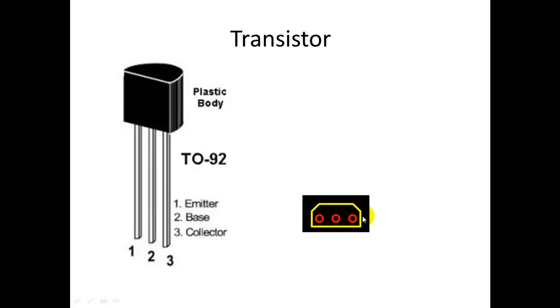It's on the top side of the circuit board, which will assist us in figuring out the correct orientation of the transistor. So here it is important to have the flat side facing down, facing this direction, and not place the transistor the other way. It could fit the other way if you place it, but it will not function because the emitter and the collector, pins 1 and 3, will be switched, and the transistor will not operate. Actually, it could also be damaged.